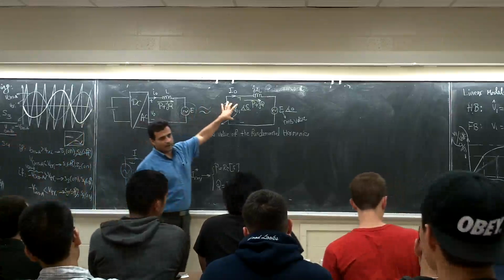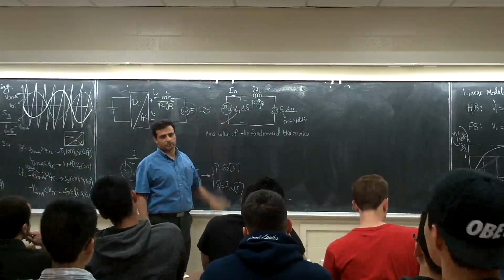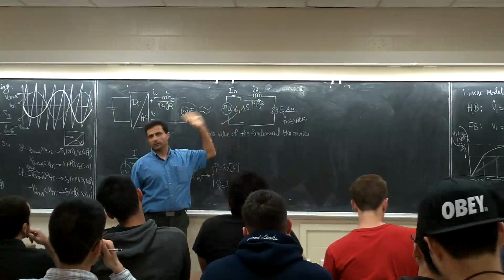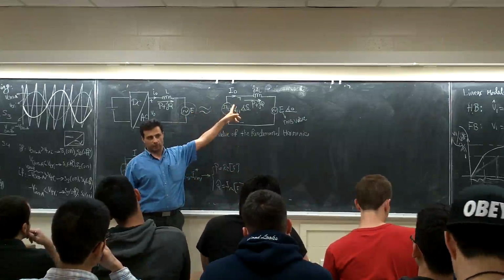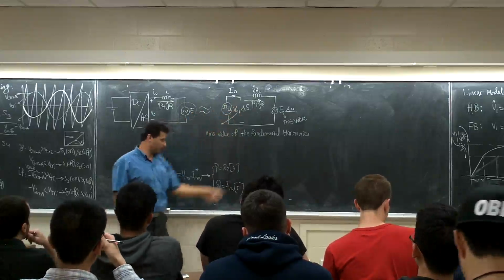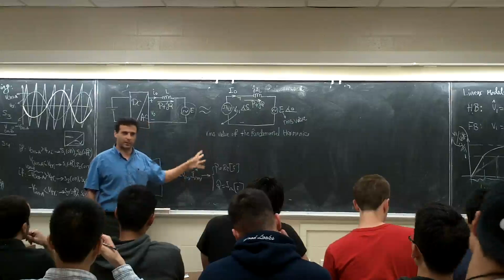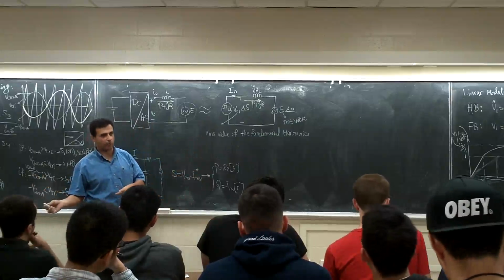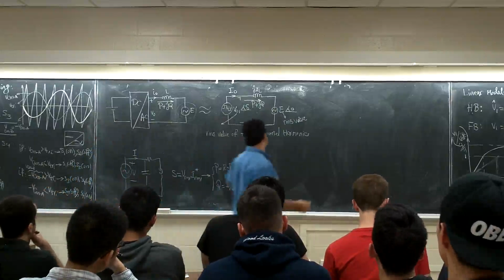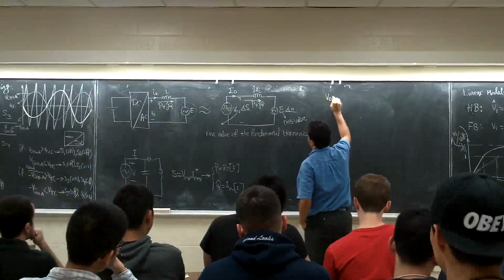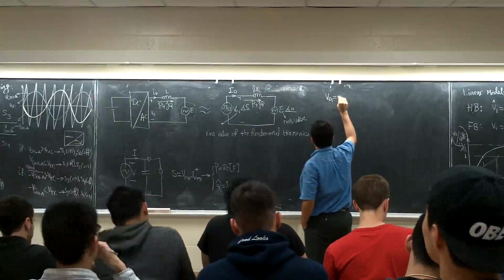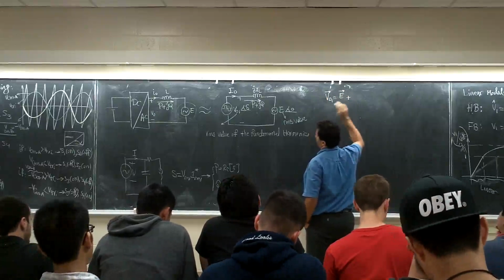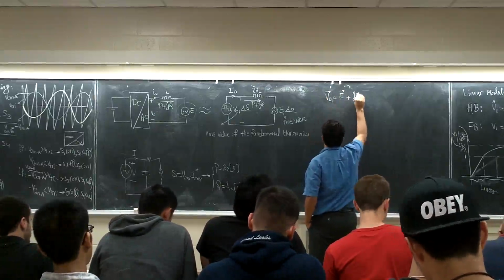I want to calculate the active and reactive power for this guy. What should I do? I know the voltage already is VO1 with angle delta. I should calculate the phasor of the current, right? If I have the phasor of current, I can take this one times this conjugate. The real part is going to be P and the imaginary part is going to be Q, right? But before going there, let me write the KVL here. KVL: VO1 is E plus JXL IO,